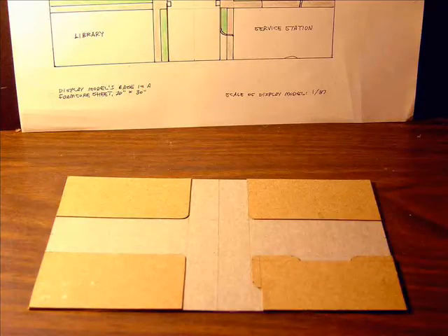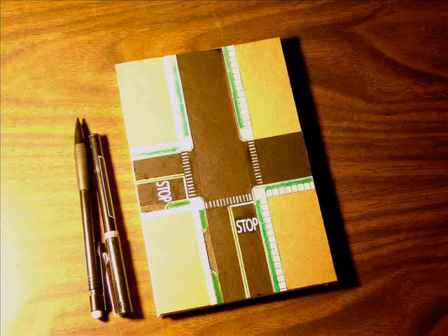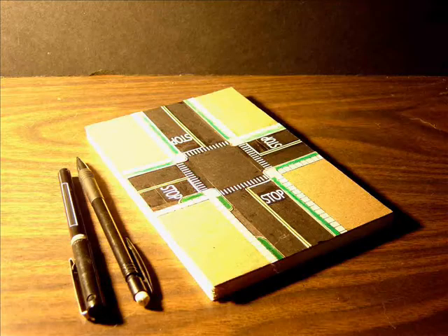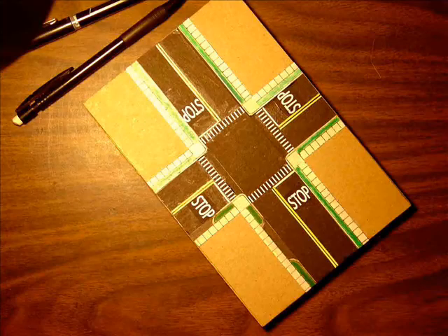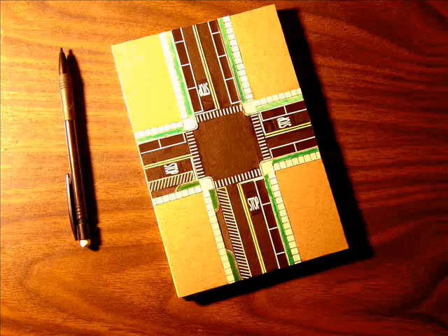The building sites are made from boxboard cut to the shapes dictated by the planning diagram and then cemented to the baseboard. Colored paper cut to shape from artist pastel and charcoal drawing pads are cemented onto the areas representing the streets and sidewalks. For the sake of uniformity, pavement markings are drawn on a computer screen and printed on a computer printer before being cemented onto the model. The planning model is built to a tiny scale, where every inch of length represents 29 feet in the real world.